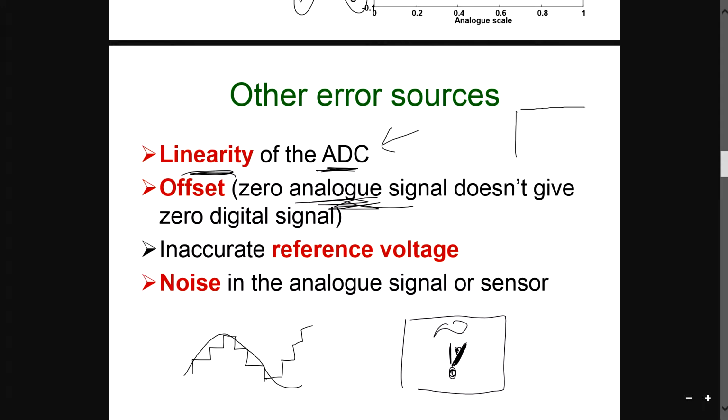I repeat again, normally if you look at the weighing scale, it should be at 0 when you didn't step onto it. However, the bar itself doesn't show 0, but somewhere over here, maybe like 0.5. So this is an offset error, because you didn't set it properly and things like that.